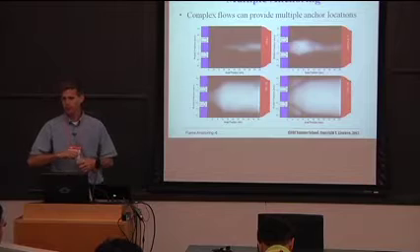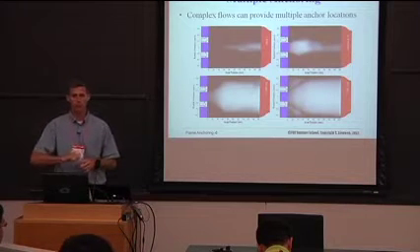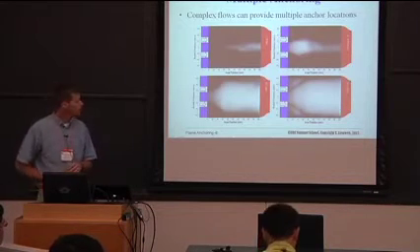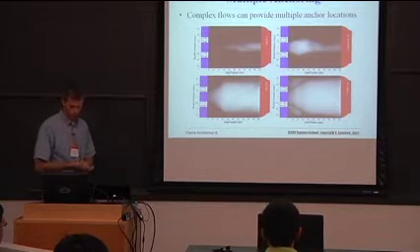Okay, now what makes life really interesting is that in most realistic geometries, particularly in swirl flows, and every commercial gas turbine out there today has swirl flows, so this is why I'm going to talk a lot about swirl flows, there's actually not one anchoring location, there's multiple anchoring locations.